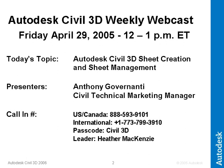Another one here: when you jump to an adjacent sheet generated by the map books, does the title block info update accordingly? Yes, that's something about the values that are added into those title blocks. It pulls the sheet name, or however you set it up, either the sheet name or the sheet number, and so on. So as I jump through those DWFs, sheet 1 is actually in the title block named 1, and so on and so forth. So that does correlate.